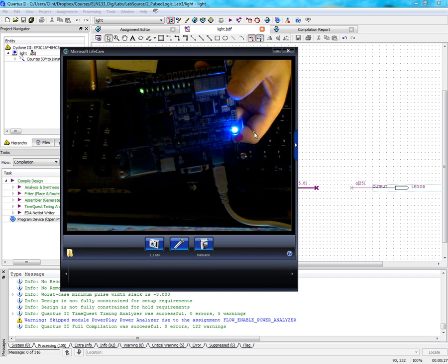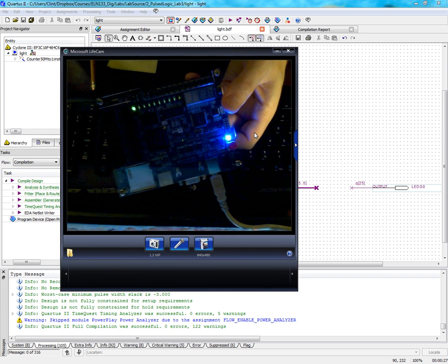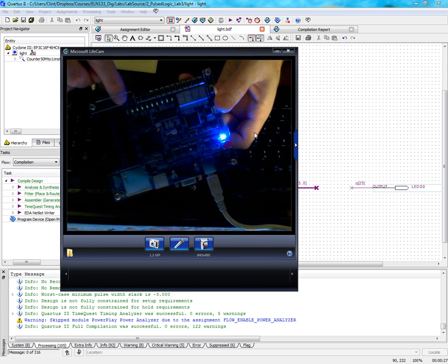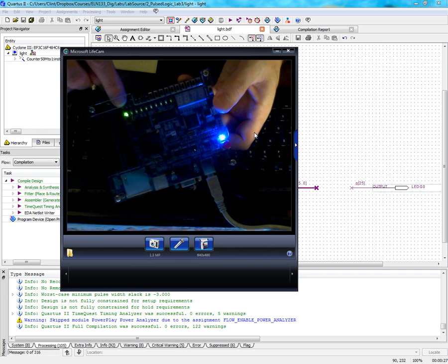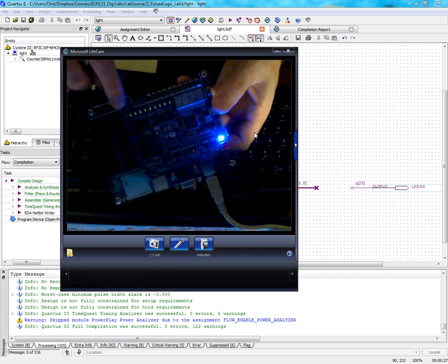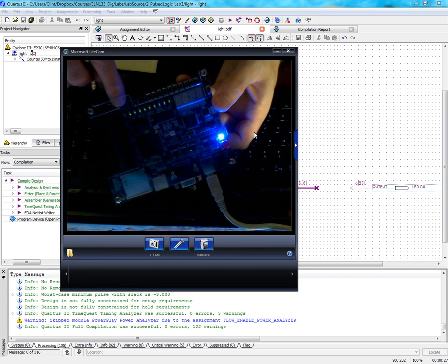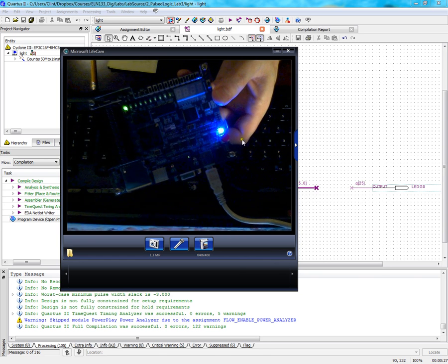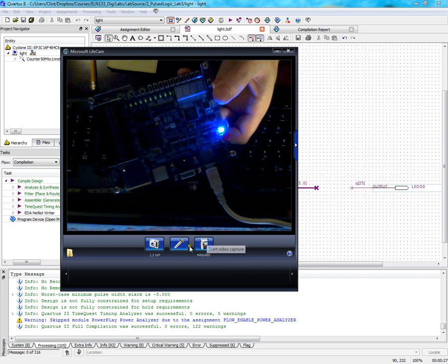And then you can look to see that your light here is blinking, at about 1 hertz, which is once per second. So now you should be able to do your lab, which is like an inhibit type function where if you push a button, the light should stop blinking. So you should be able to do your lab now. Alright, that is it, and I hope you have good luck on your lab.